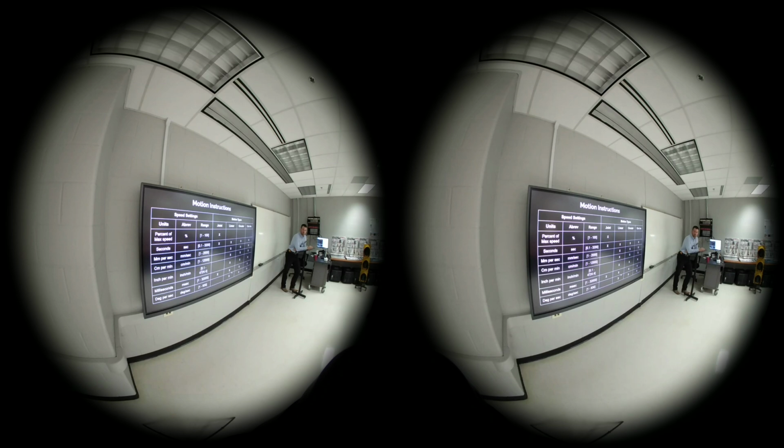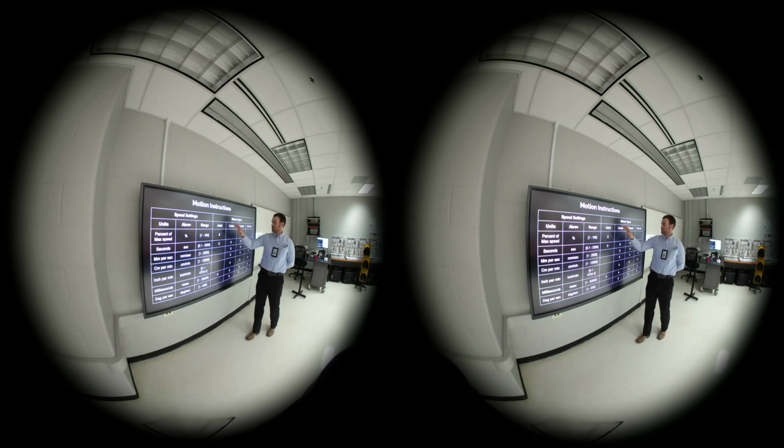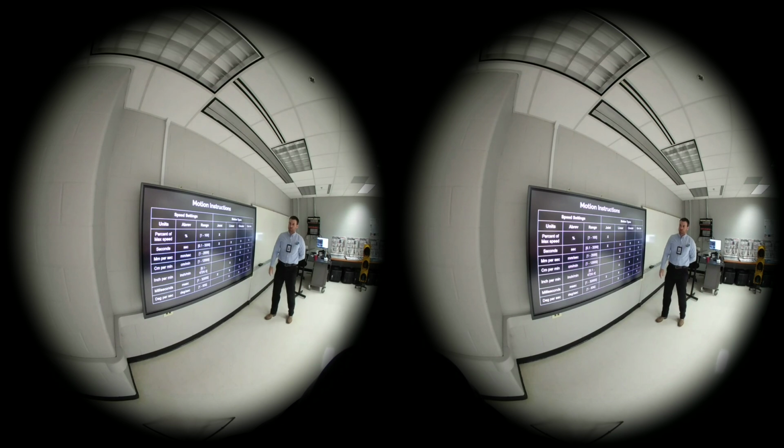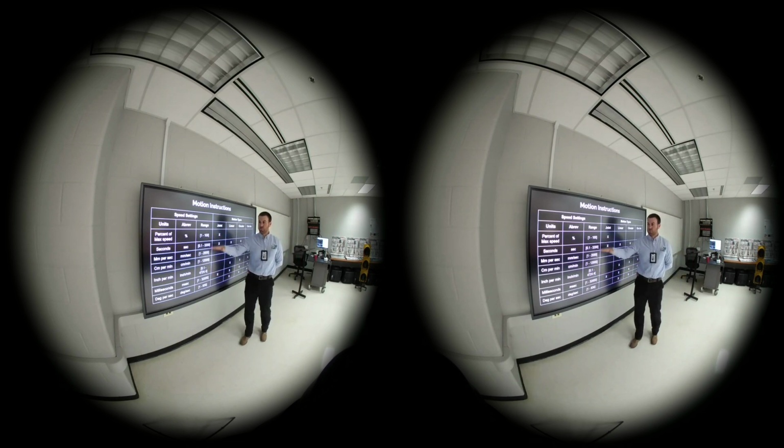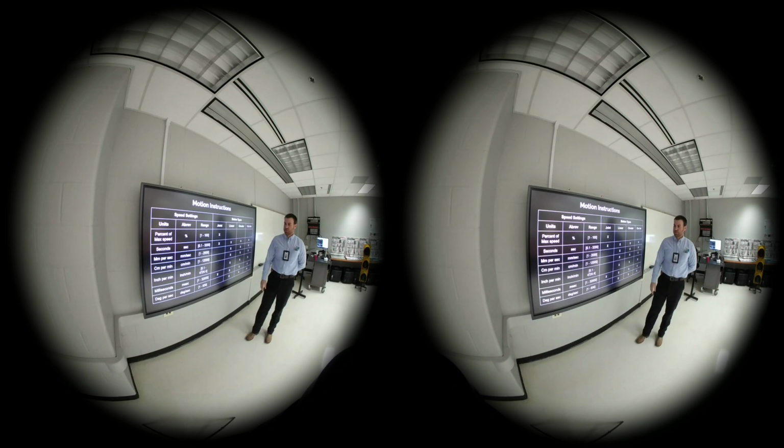So we're going to start off with a little bit of review on motion instructions. We have our speed settings, and the speed settings correlate to different motion types. This is at the beginning of the line call. So you have your J, your L, C, and circular arc, and this gives you the range of what speeds you can put in. You can do a percent of max speed, seconds, millimeters per second, centimeters per minute, inches per minute, milliseconds,